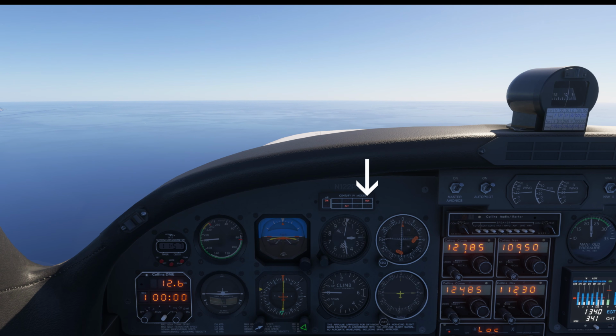Reverse mode works the same as approach mode, but the autopilot will track the tail end of the needle. Instead of flying the course inbound, it will track the course outbound. The main use of this mode is to fly the localizer back courses or outbound VOR legs without the need to rotate the course setting 180 degrees. The autopilot will automatically compensate for reversed CDI movement.